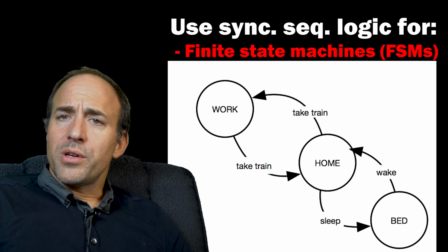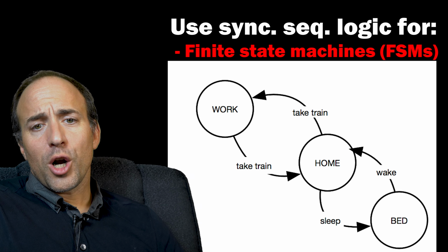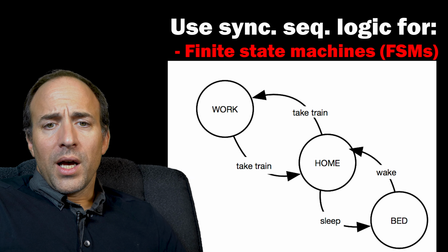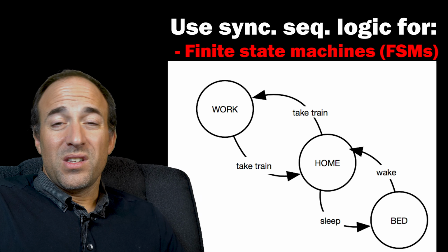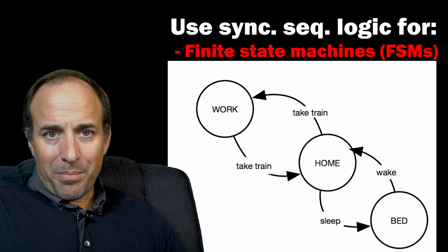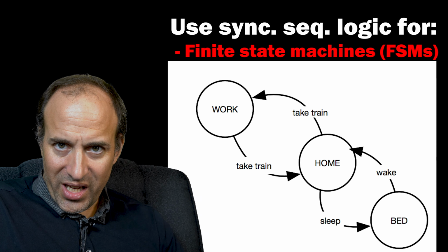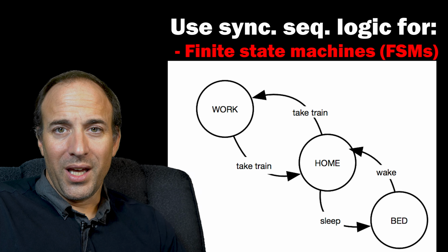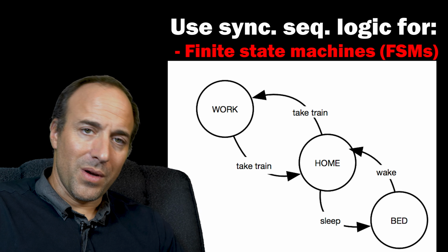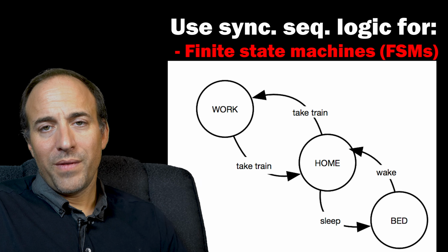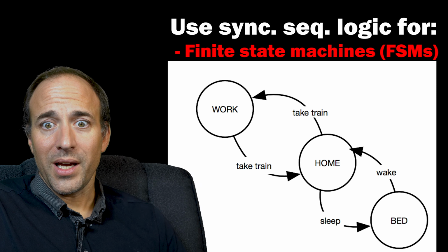State machines can also be used as interfaces for arbitrated buses, or logic that, for instance, processes network packets. Now, the reason why you need one for that is because packets are usually received in pieces, and each piece of a packet needs to be handled differently depending on which piece is received. So as the packet rolls in, it may take multiple clock cycles, and the interpretation of each one of those pieces is different in each clock cycle.